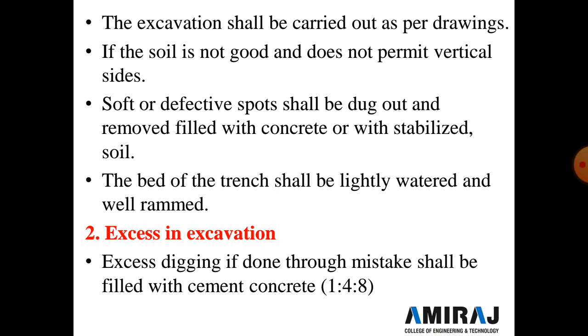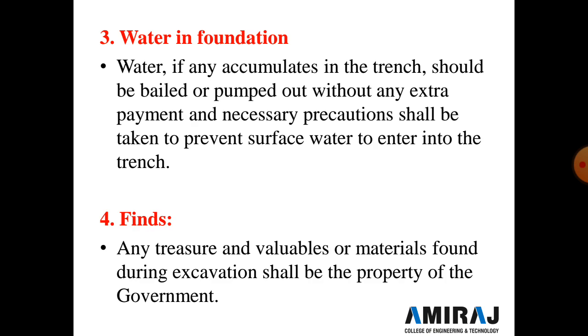And the second point is excess in excavation. Excess digging, if done by mistake, shall be filled with cement concrete of ratio 1:4:8 at the expense of the contractor. No extra payment shall be made for this. Now the third point is water in a foundation.